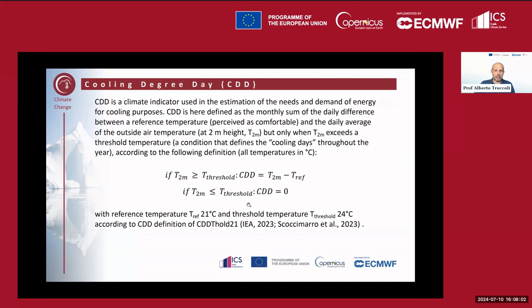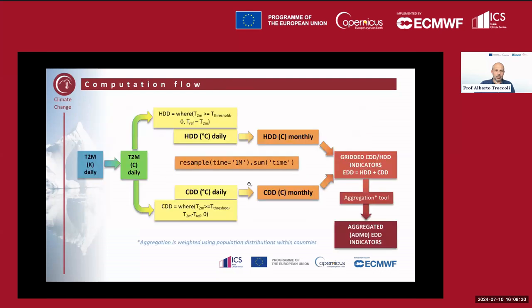And again, similar and specular definition for the cooling degree days. Once we have the heating degree days and the cooling degree days, we then simply take the sum, and that's our energy degree days.